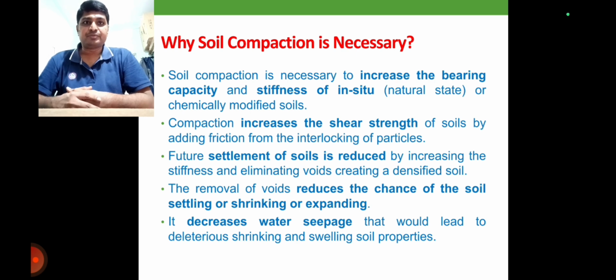Future settlement of the soils is reduced by increasing stiffness and eliminating voids, creating a densified soil. The removal of voids reduces the chance of soil settling, shrinking, or expanding. It decreases water seepage that would lead to deleterious shrinking and swelling soil properties.